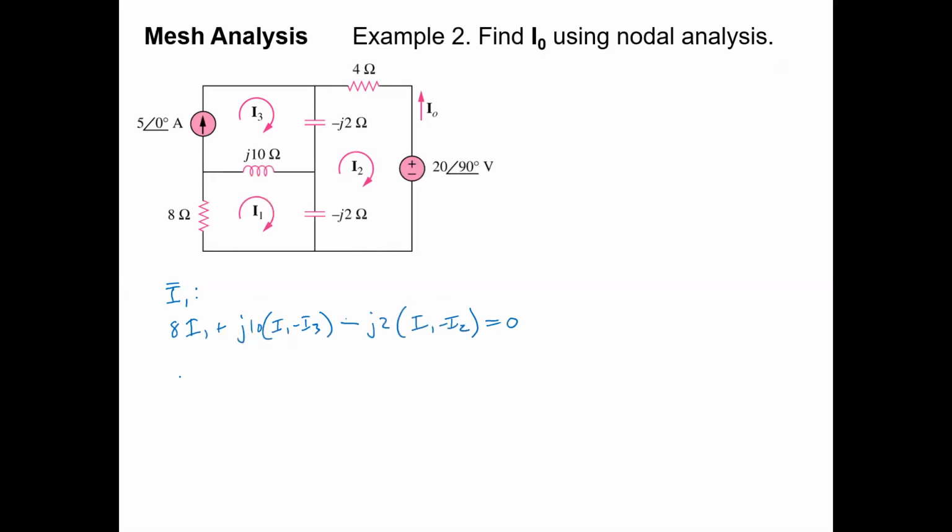What's the difference between mesh and nodal versus KVL and KCL? Yeah. So mesh is based on KVL. It applies KVL in a very systematic way. Nodal analysis is based on KCL, and it applies in a very systematic way. You can apply KCL anywhere, but if you apply KCL to these so-called node voltages that we describe relative to some reference point in your circuit, that's nodal analysis.